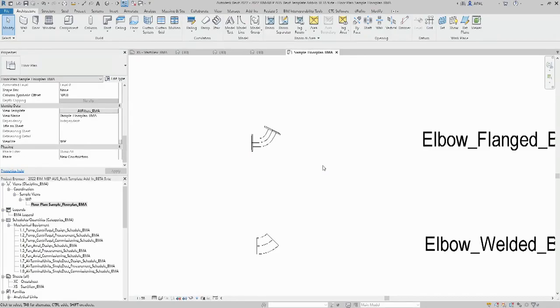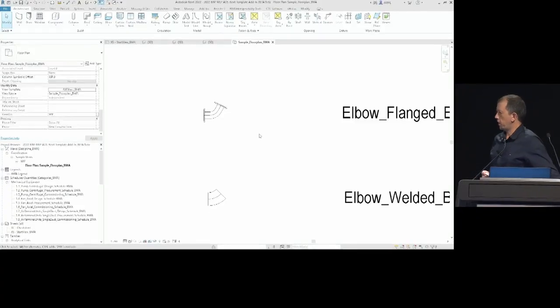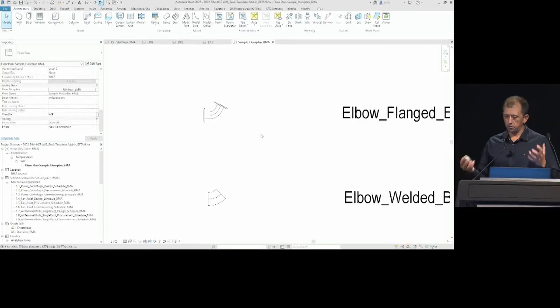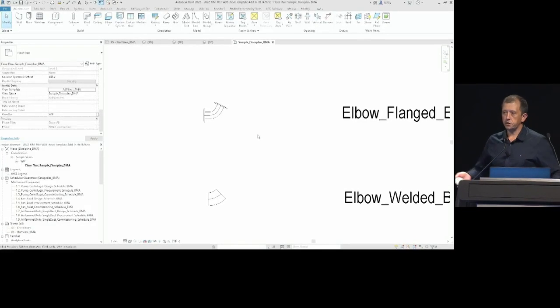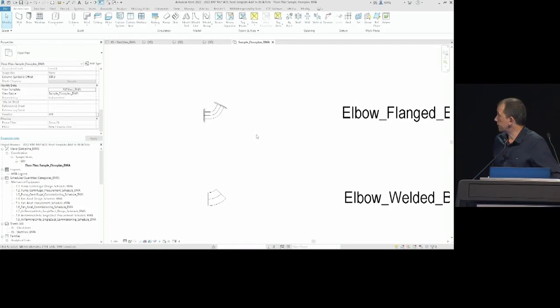Some designers just don't want to run into these warning messages all the time, and routing not possible, and that stuff. We try to keep it flexible. Also, when you think of scan to BIM workflows, there's something that's happening more and more: people model from a point cloud, and maybe have a 50-year-old building or plant room that was scanned, and maybe you just don't have the 45 or 90 degree elbow in there. You maybe need something a bit special.